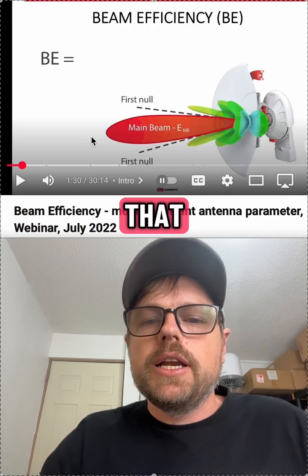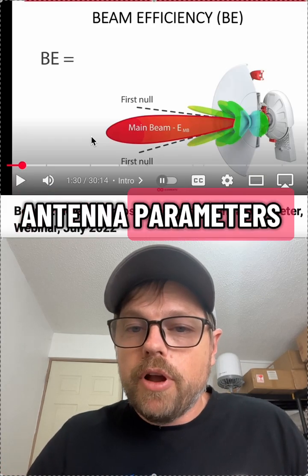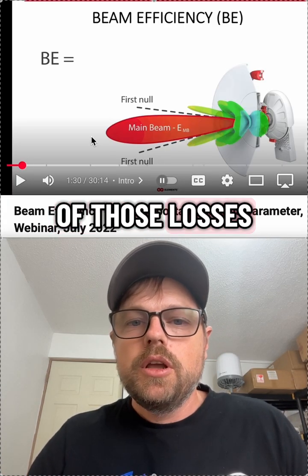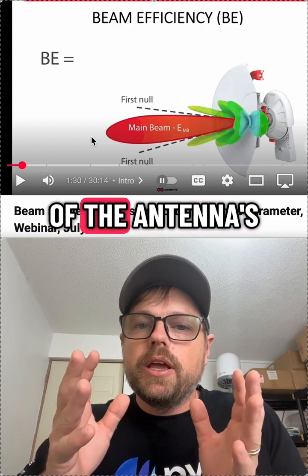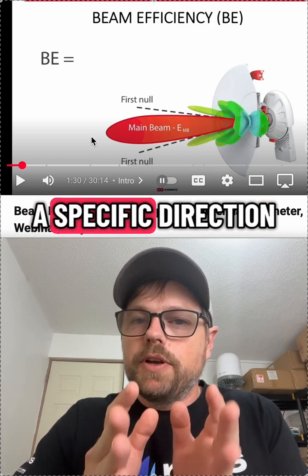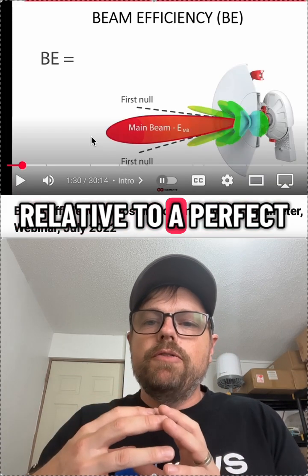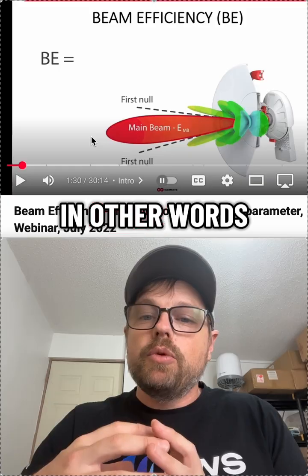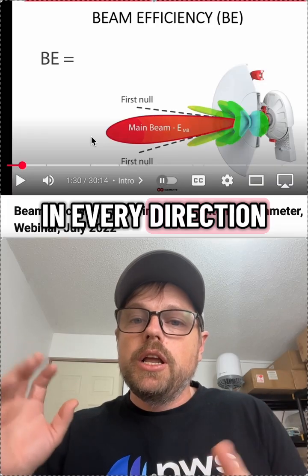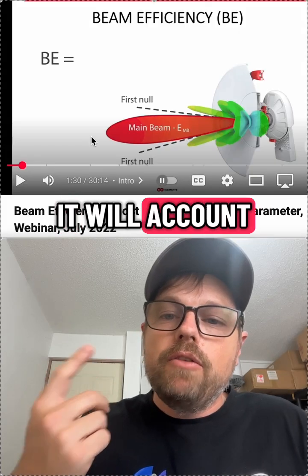And what's interesting is that while focusing on beam efficiency, they dismiss other antenna parameters such as gain, which actually do account for all of those losses, because gain is the measurement of the antenna's ability to efficiently focus energy in a specific direction. It is measured relative to a perfect isotropic radiator. In other words, an antenna that is radiating perfectly in every direction. So gain will account for VSWR. It will account for cable loss.